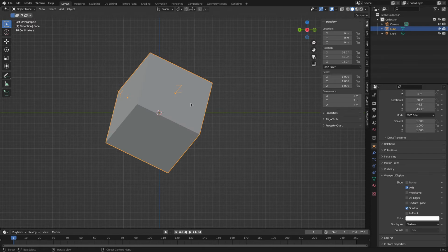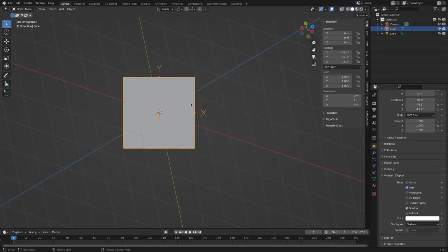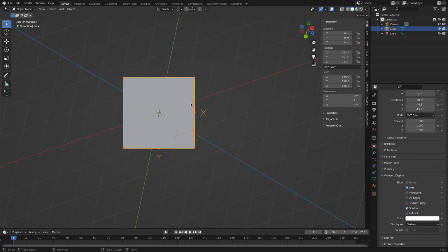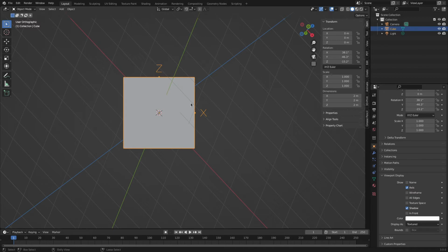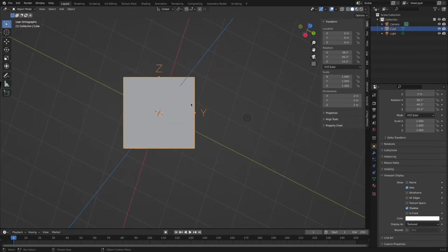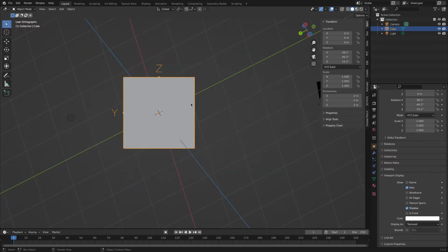But if we select the cube, it is selected. I'm going to use Shift 7, and that is cube top. Control Shift 7 is cube bottom. Shift 1 is cube front, Control Shift 1 is cube back. Shift 3 is cube right, or right positive X side of the cube, and Control Shift 3 is the negative X side of the cube's X-axis. And further, this goes for most selectable things. Most data blocks, most objects in your 3D scene have their own coordinate system, their own orientation, right?